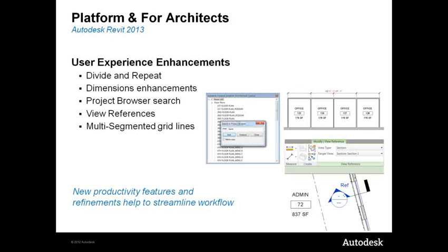Dimensions enhancements. Dimensions continue to improve based on customer feedback. There are 3 enhanced dimension styles. There is a new diameter dimension tool that includes an option for a diameter symbol location. The first enhancement is the split dimension chains features. It enables an individual segment in a multi-segment dimension chain to be selected by tabbing and deleting the individual segment. The last enhancement is a new method of display dimensions properties in equality strings. You can create an equality formula by using dimensions parameters and static text that can be built into a string.